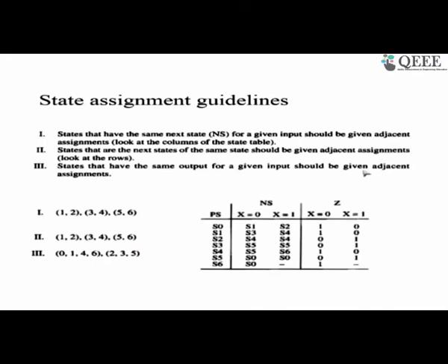Next, what we should do is a state binary assignment for these states, in which case there are 7 states, 0 to 6. We could allocate 3 bits and encode them as 000, 001, 010 and so on. But this way of arbitrarily assigning states in increasing order as we indexed the states may not lead to an optimal realization. So we should try to encode the states in a manner which reduces the realization. For that we have certain guidelines for assigning states.